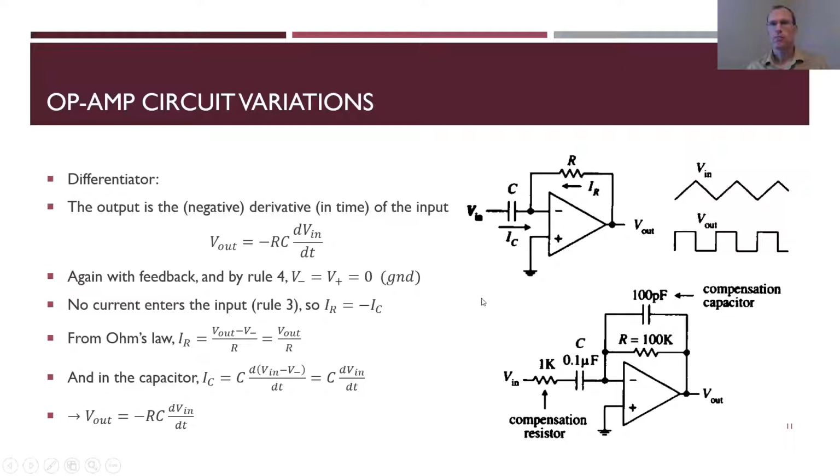If you have an integrator, might as well have a differentiator as well. So something to integrate, also have something to differentiate. This is similar to the circuit we had before, but alternate the positions of the capacitor and the resistor. Kind of like how we did this for the high pass and low pass filters, same deal here, just reverse them, and that does the opposite. So in this case, I have a differentiator. Again, I have a negative derivative because I'm into the negative terminal. So negative derivative in time, so my out is the derivative of what's coming in.